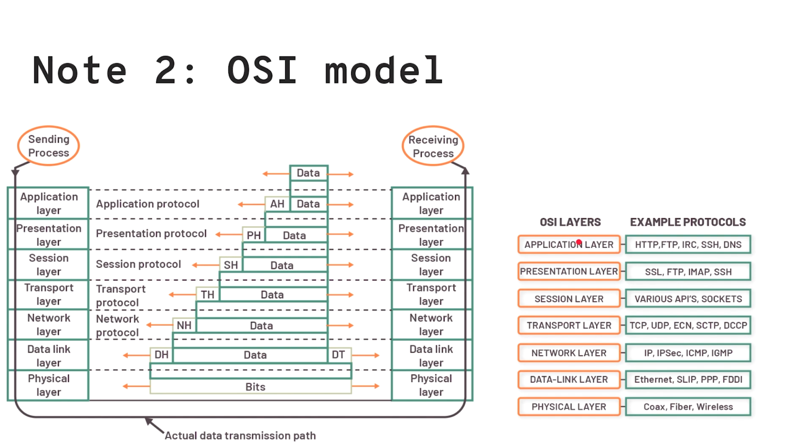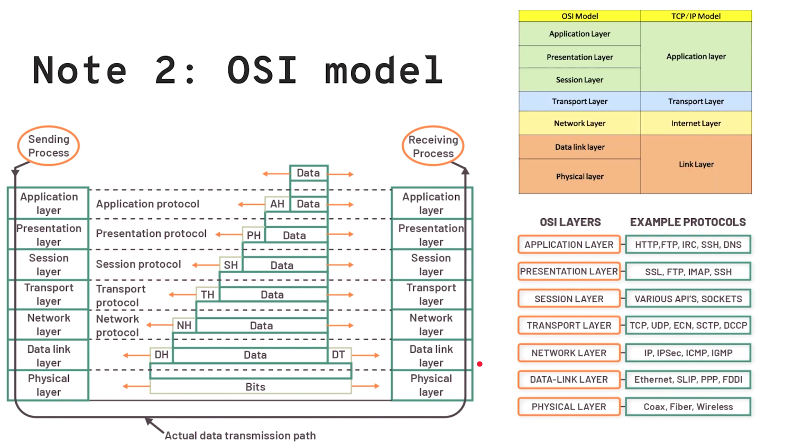And this distinction here is important. Understanding the OSI model is important because sometimes industrial protocols look like regular protocols with a modified physical layer, modified data link layer. That's why the refresher is here. And I mentioned the TCP/IP model merges the 3 layers, application to session, into an application layer, and the data link to physical layer is also merged into the link layer. But we're concerned about the OSI model here because most protocols are not regular TCP/IP protocols in the OT environments.